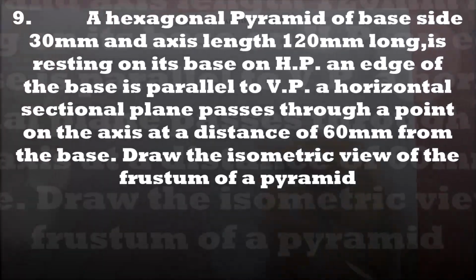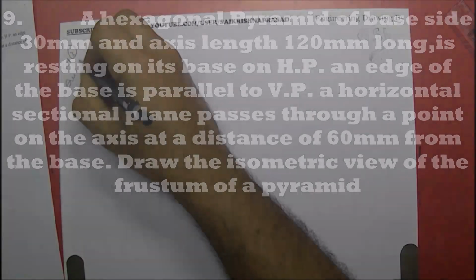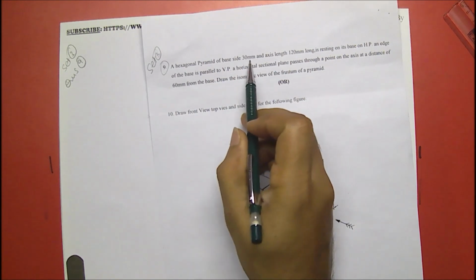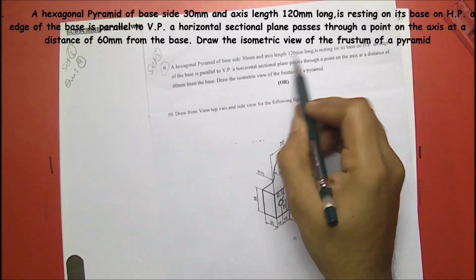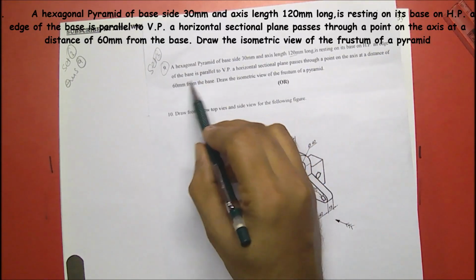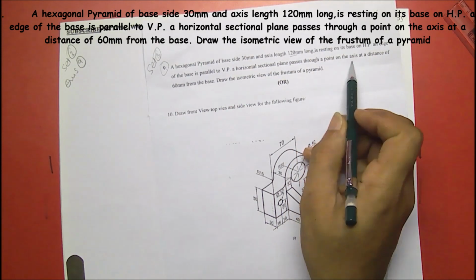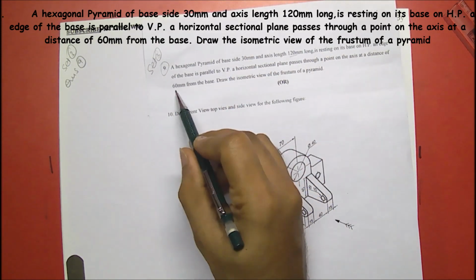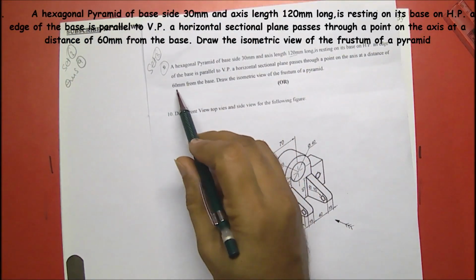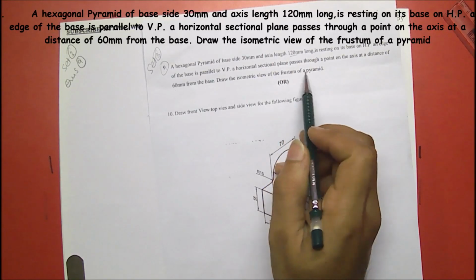Question 9. So given data here, hexagonal pyramid of base side 30, axis 120, resting with base on HP, and the edge of the base is parallel to the VP. Horizontal section plane passing through the point on the axis at the distance of 60 mm from the base. Means from the bottom it is cutting 60 mm above the base. Draw the isometric projections of frustum of a pyramid.